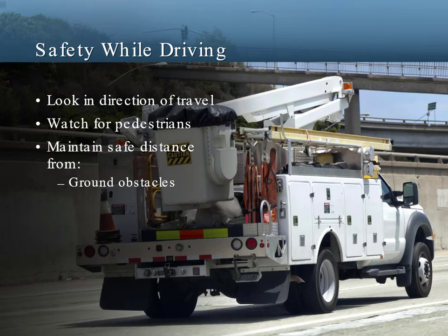Also, maintain a safe distance from any overhead obstructions. And limit travel speed according to conditions. That means considering ground surface, ground slope, other traffic in the area, location of personnel, and so on. Do you always drive vehicles equipped with aerial lifts safely and follow the rules reviewed in this slide?